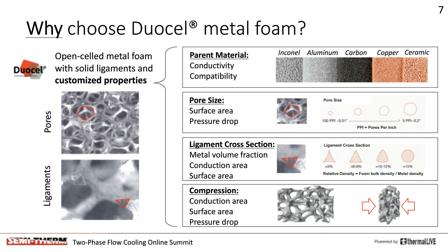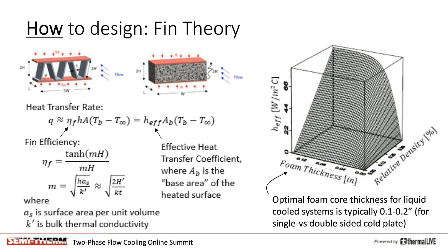But how do we go about designing cooling systems with this seemingly complex material? The design process is actually very similar to that of fins. Consider the fin and foam cores depicted above. In either case, you can express the heat flux in terms of a fin efficiency or in terms of an effective heat transfer coefficient on the heated surface.